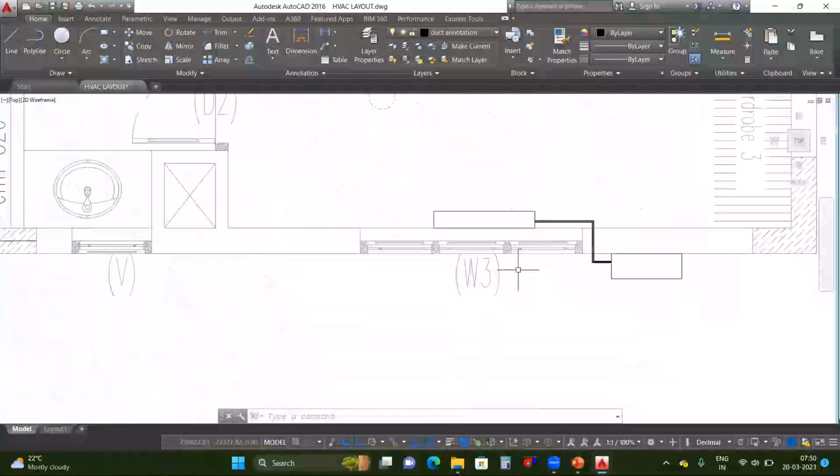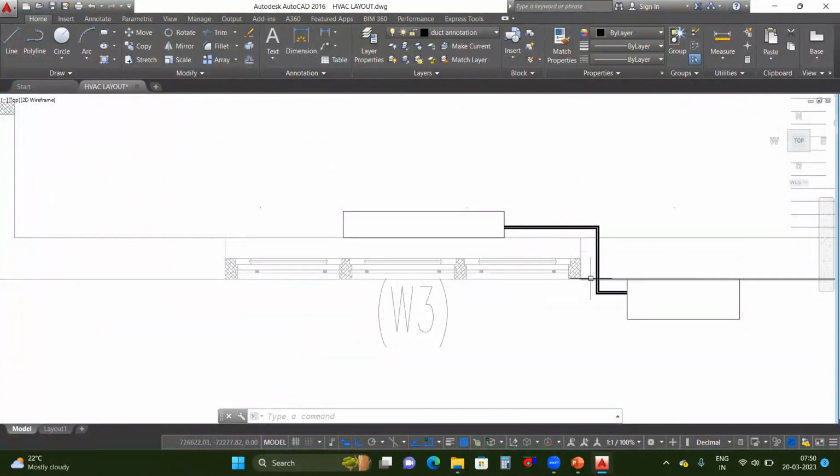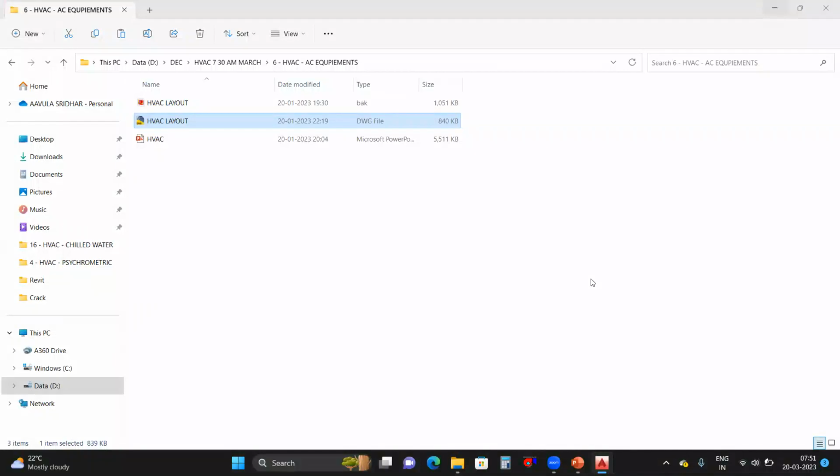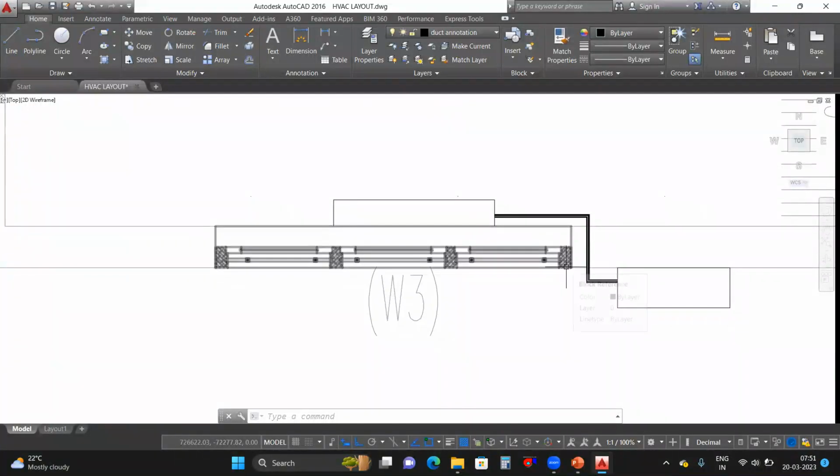so here only one thing that we need to take care. So from indoor unit to outdoor unit, the distance should be minimal. So we don't need to increase the copper piping length. So if we increase the length, the efficiency will be less. So consider that is approximately 15 meters, you can consider that. Okay,